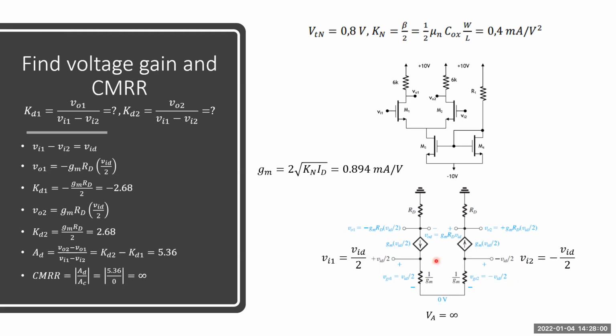And these are the dependent current source values in the small signal model here. But I want to draw your attention to the current direction in the small signal model because it's reversed, right, for these two input differential transistors.